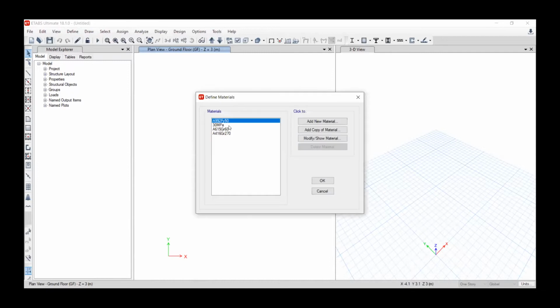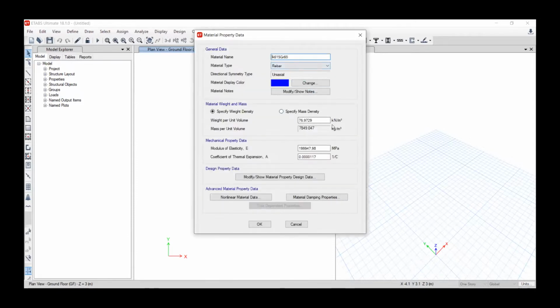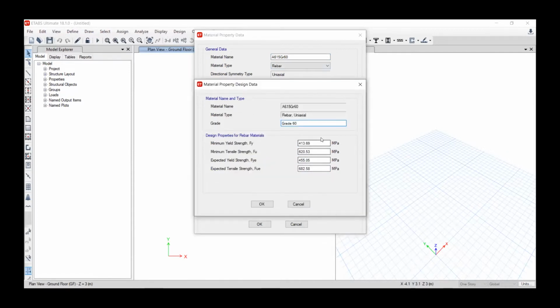Here we have defined this one, 30 megapascal. And now we are going to define the rebar, which is still the same. It is the same for the 200 gigapascal or 200,000 megapascal. The same we have with f prime c. I will keep it the same also. Maybe I can change this to 420 as a yielding. I will change this one only for the yielding.